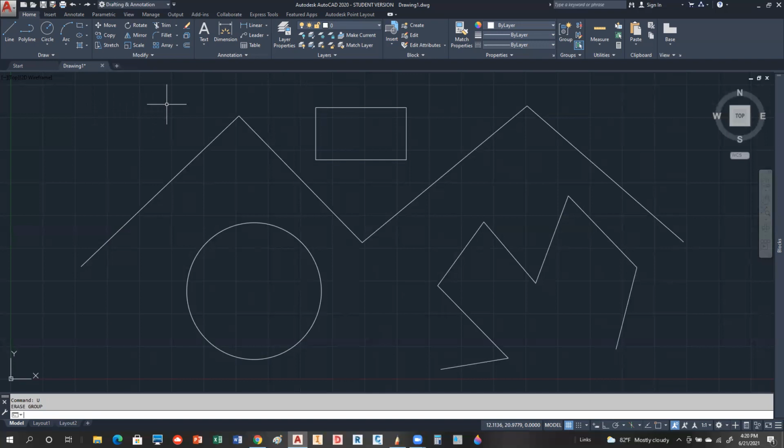Okay, so you want to be really, really careful with all. But it's very important for some commands or some things that you do. Like if you have to move your whole drawing from one position to another, it's very convenient to select everything using the all option, because you make sure that you get everything. Now, it is possible to protect objects, and we'll probably be talking about that, I think, next week. Up here in these things called layers, you can protect objects. So even though they're visible on the screen, they're not selectable. And in that case, all will not be able to grab those objects. Okay, so you kind of have to look at that.